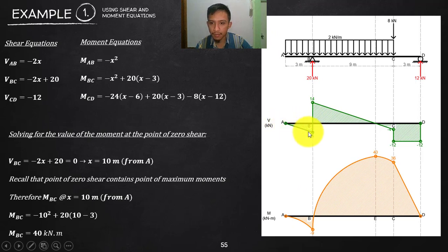That will now be a straight line going up abruptly, and how is that a straight line? The same reason. Your loading here is -2, which is constant, therefore that is a straight line going down. Slope is going down. And if you try to get a slope, rise over run, the rise here is -6, the run is 3. So -6 divided by 3 is your loading, which is your slope. Do the same thing here. That is 9. Is this 9? Yes, this is 9. And that value is 14.